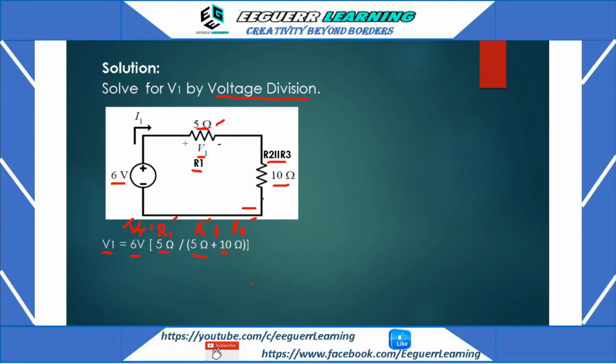So by getting the values for those resistors and voltage, let us replace. So replacing them, 6 volts you just retain, and 5 ohms retain, and we just solve first for this one, which is 5 plus 10 will give us 15 ohms.